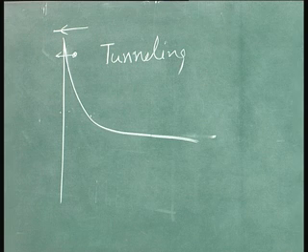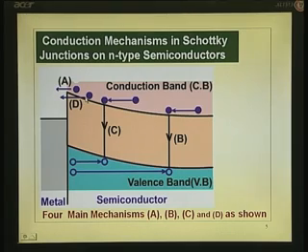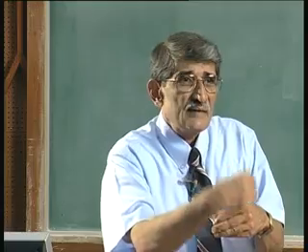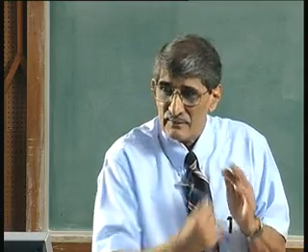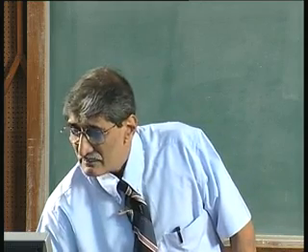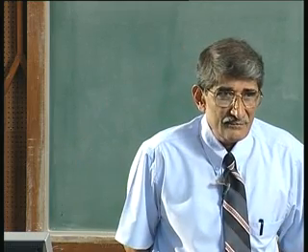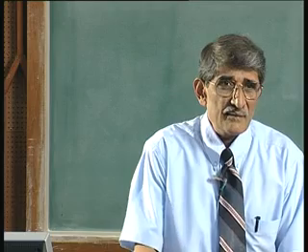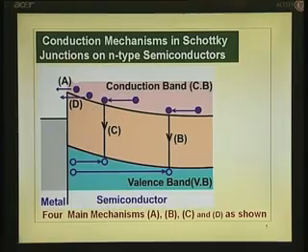The top one is thermionic emission, and this one is called thermionic field emission, TFE, because these electrons have enough energy because of thermal energy here, and this is because of field. The slightest field will push it across, because it can easily occupy the other portion, as its wave function goes onto the other side also. So, thermionic field emission is another name given to that. Okay. So, you will hear terms like thermionic emission and thermionic field emission; these are slightly different mechanisms.